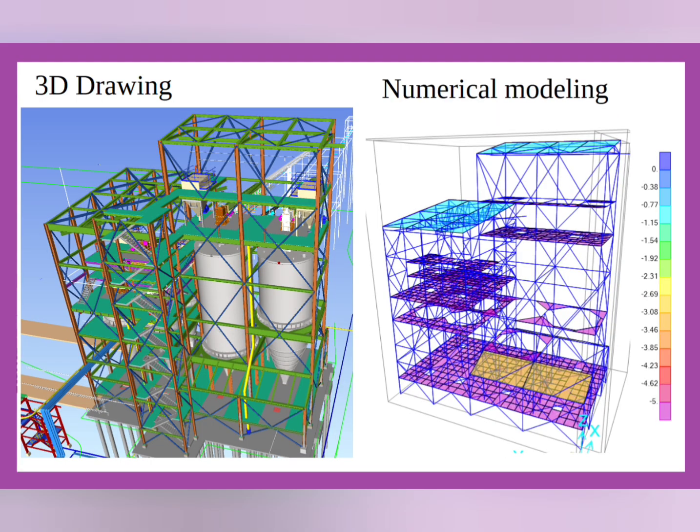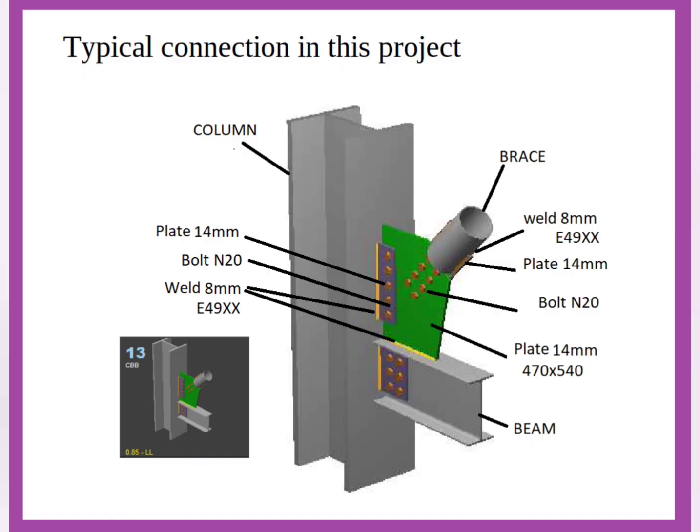Furthermore, the integration of two engineering software, SAP2000 and RAM CONNECTION, is discussed in the video. Both will be used to automate the process and organize the large amount of data and information collected on the building. Here, bolted connections will be thoroughly analyzed, but welded hybrid connections will also be discussed. Bolted connections are modeled by pinned joints. Pinned joints are created in software by releasing bending moments.